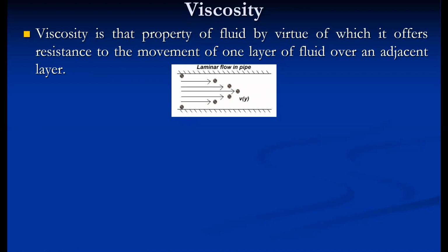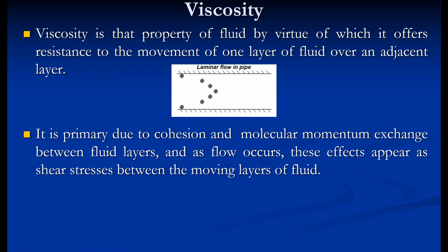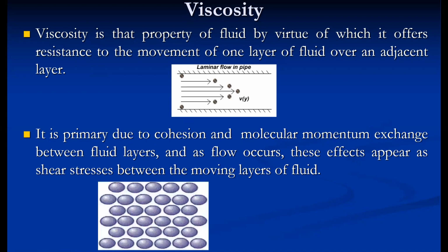In brief, you have to remember that viscosity is resistance to flow, primarily because of cohesion and the molecular momentum exchange between the fluid layers. A thicker fluid generally has a higher viscosity because there is more cohesion in a thicker fluid, and also some momentum exchange. As the temperature increases for a liquid, because of this changing momentum, the viscosity decreases, or the flowability increases.